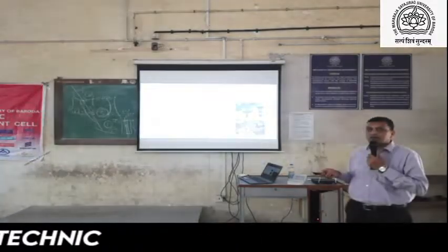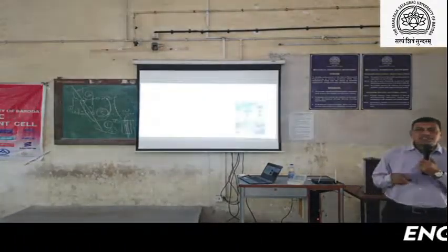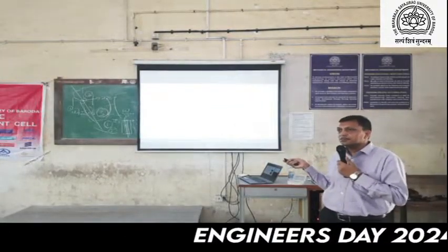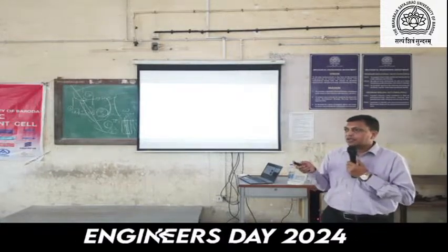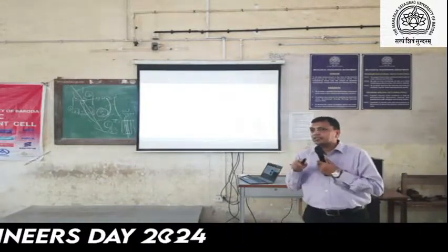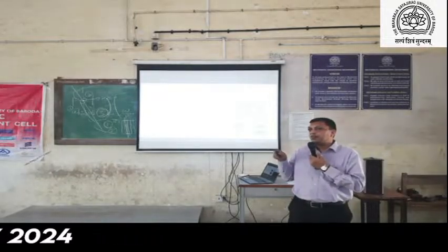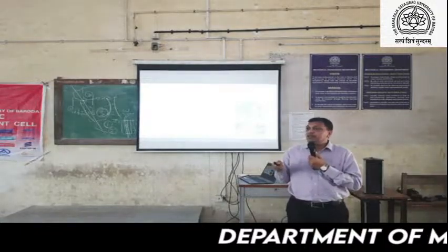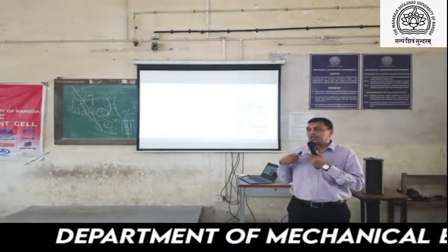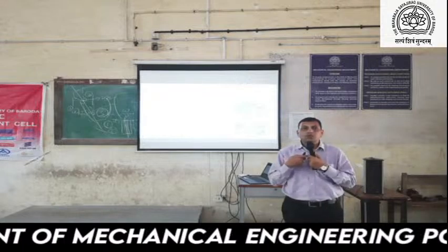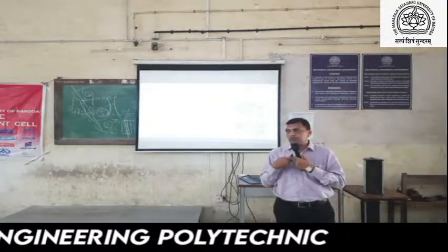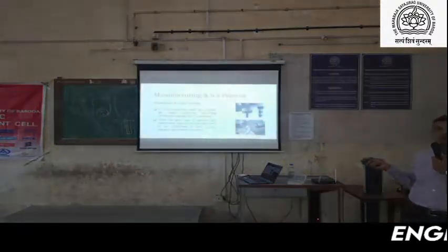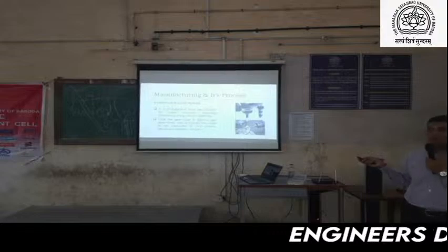Then inspection of the profile. Basically it is used for very special cases only, and the profile is measured on the tooth and it generates one graph. That graph is related to the drawing we already have, and it should be matched with that. Another thing is that if we are making matching components for the first time, we have to check the profile of both the tools, and they should be matched. This will help us get good contact as well as backlash maintenance.